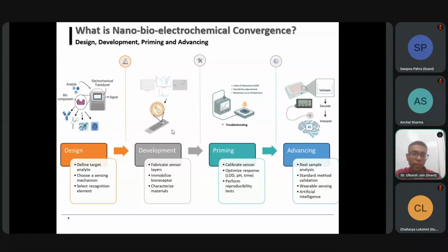Just in a nutshell, I can tell you that nanomaterials can give you a proper signal above the threshold value, so that we can get a detectable range. For example, if I'm working on a current-based detection, and my electrode material is not giving information which is detectable, then I need to coat certain nanomaterials after their selection. These nanomaterials can enhance the conductance on the electrode surface and give more information and a detectable range where we can really detect a particular signal. This is actually very important.